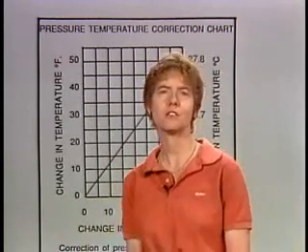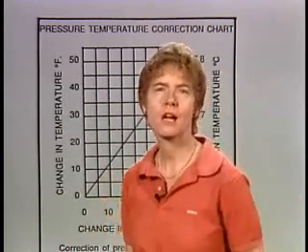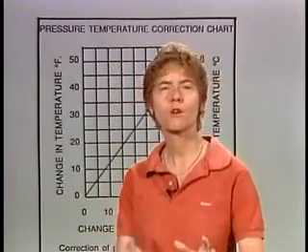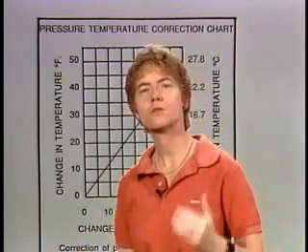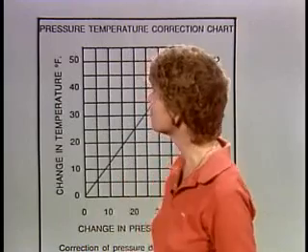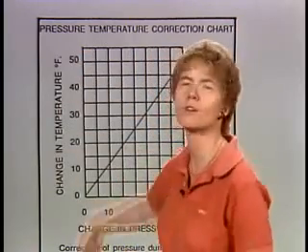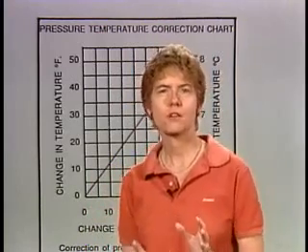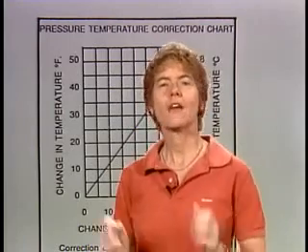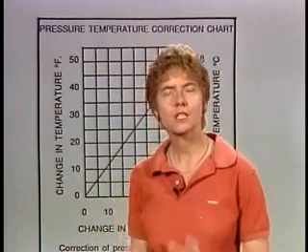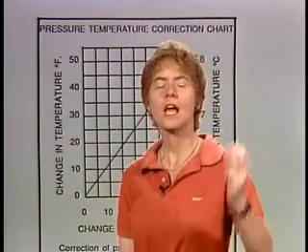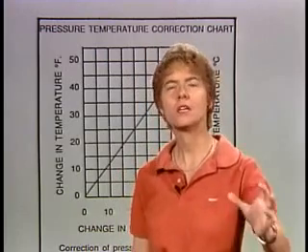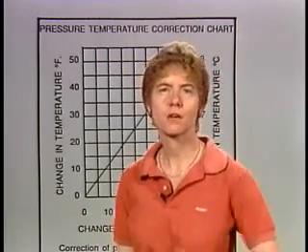Okay, so what's the FAA going to say to you? They're going to say to you that 1 hour after an oxygen system was charged to do a leakage check, the oxygen pressure gauge read 460 psi and the temperature was 63 degrees Fahrenheit. Okay, one thing we know right there, we're going to be working with degrees Fahrenheit as far as our temperature is concerned. Now, 6 hours later, the temperature had decreased to 50 degrees Fahrenheit, and they want to know what pressure gauge readings would be acceptable to remain within the allowable limits, and they throw in the fact that a 5 psi change is the maximum allowed in a 6-hour period and still have an acceptable leak test.